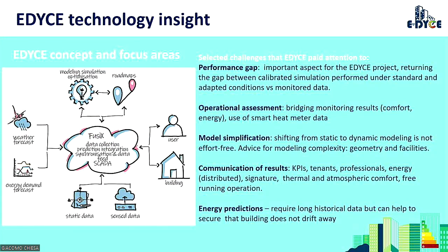Regarding the key challenges of the E-DYCE project, the first is the performance gap, which is the difference between the theoretically anticipated energy and the actually used energy in the building that is monitored. The second challenge that we covered and addressed is the operational assessment, which is about bridging and collecting the monitoring results for comfort and energy, both in the building, and also by using the smart heat meter data for determining the space heating and domestic hot water separately.